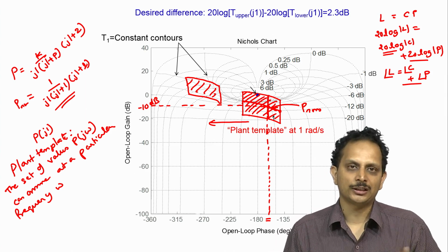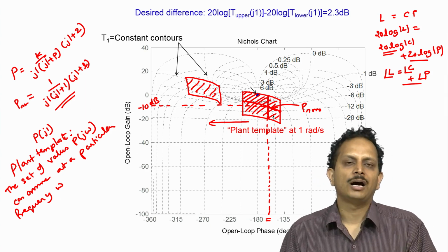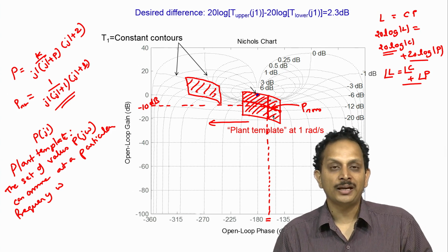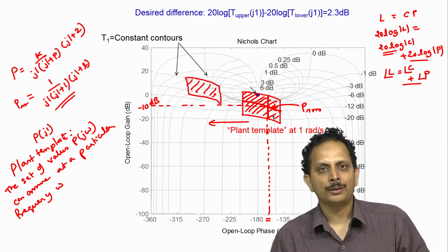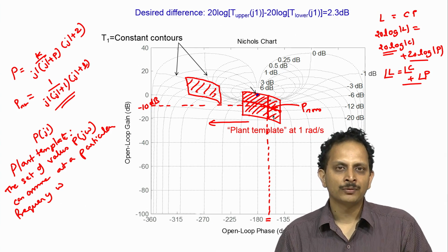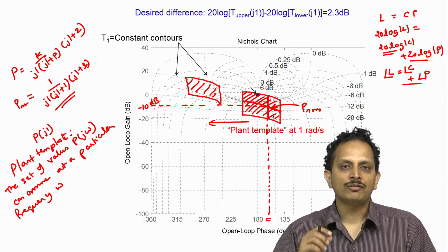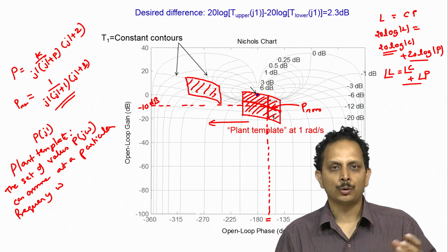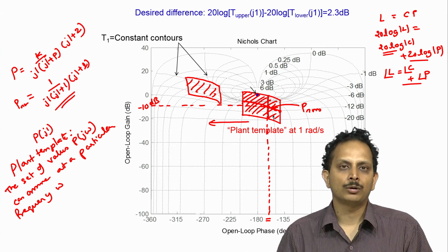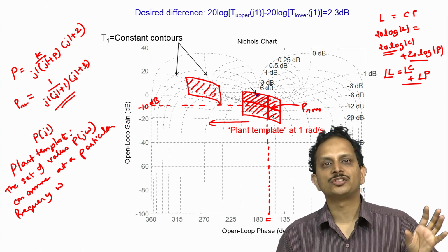And this is the attraction of a Nichols plot based design, because if you go back to our discussion on the challenges introduced by an uncertain plant when we are trying to represent performance specifications in the Nyquist plot instead of the Nichols plot, we notice that when we multiply the plant transfer function with the controller, then the area within which the plant transfer function could assume values in the Nyquist plot not only got rotated but also got scaled up.